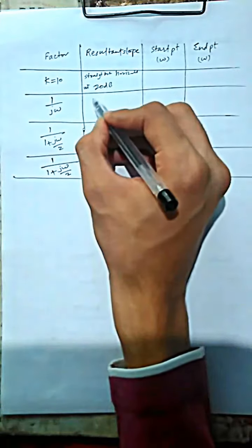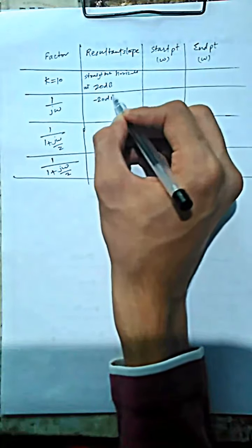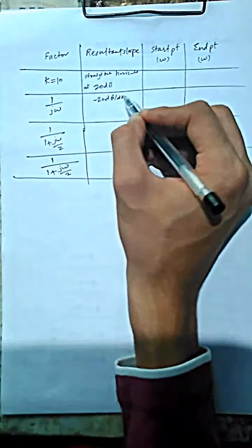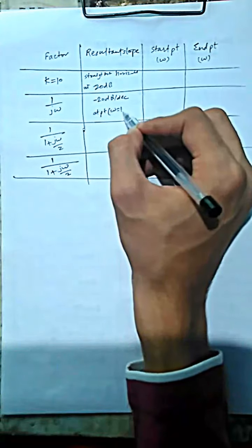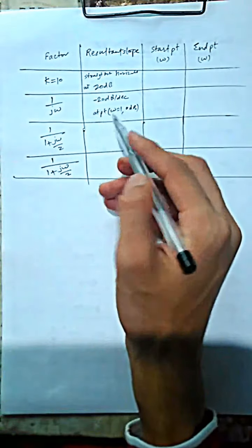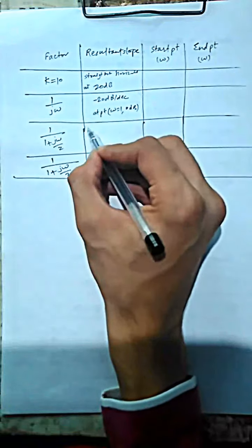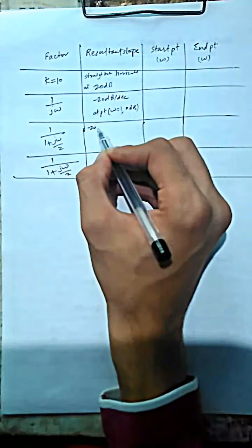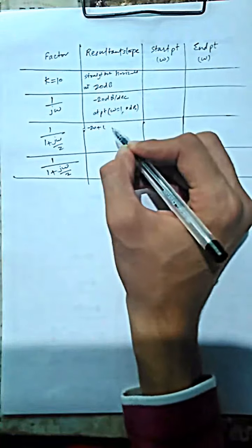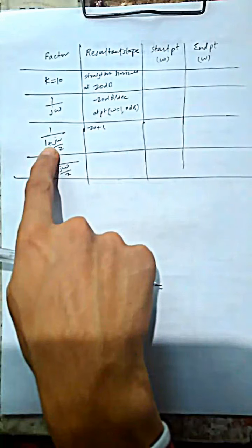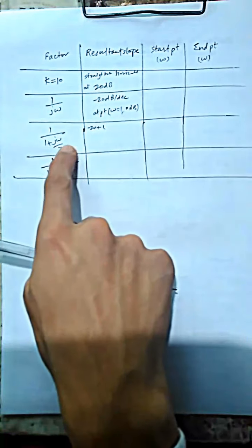For the second one, we had a slope of minus 20 dB per decade passing through the point omega equal to 1 and 0 dB. Now here the task starts. Whatever the previous slope is, write the same, and we'll sum the individual factors' slopes. The slope for this factor, as we have said, depends on omega.